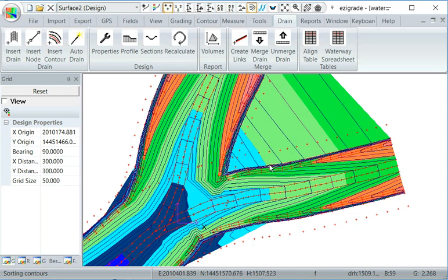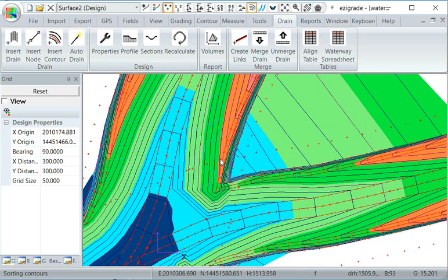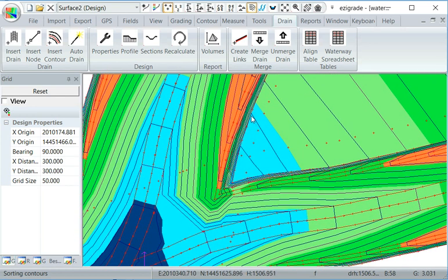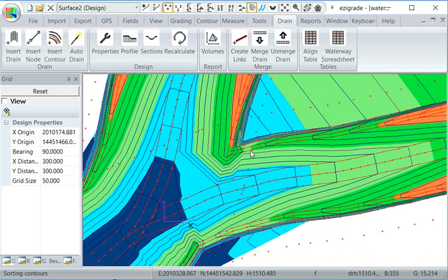And it's drawn these break lines. So what it's done, when it's found it's intersected with an existing break line, it starts at the outside and intersects the respective edges. This is where those codes come in when you define your templates, and that's why these are cut here. They don't go any further, they've been broken off and the bits in the middle have been taken out.